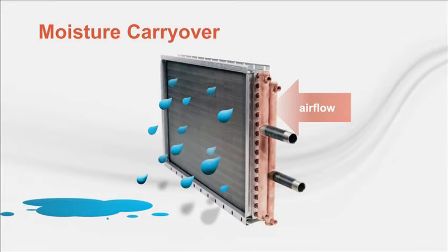When a coil dehumidifies, it must be selected to prevent moisture carryover. Too high of a face velocity through a wet coil can result in some of this condensed water blowing off the fin surfaces onto the downstream components in the air handler or duct system. In some cases, moisture carryover can cause damage to the HVAC equipment and contribute to other moisture-related problems in the building.